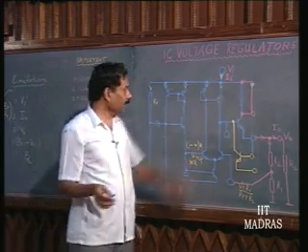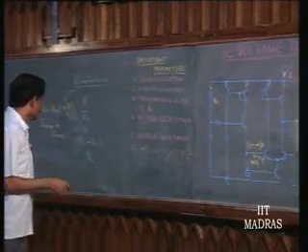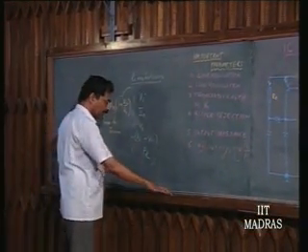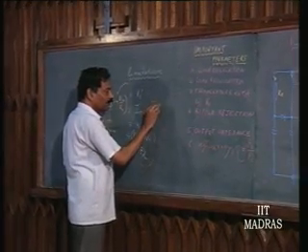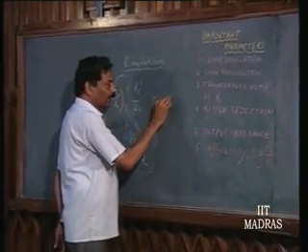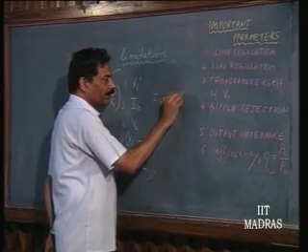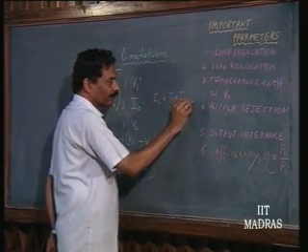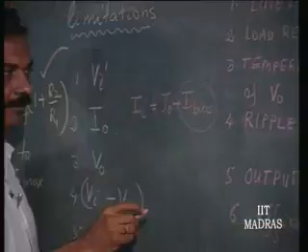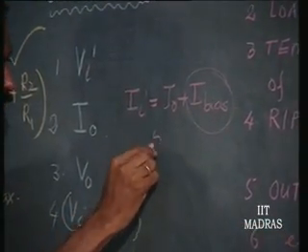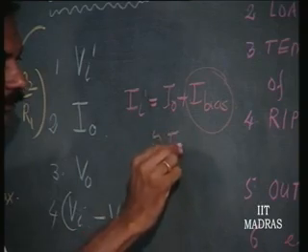So, essentially in a regulator we are going to have this consideration, I is going to be I naught plus the various bias current required, and this has to be made very small, so that this is very nearly equal to I naught.